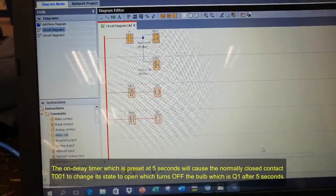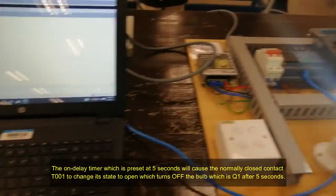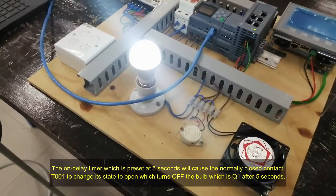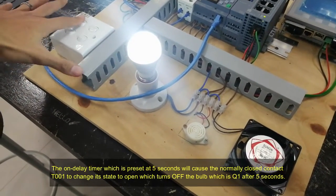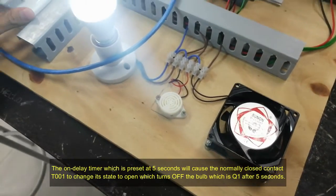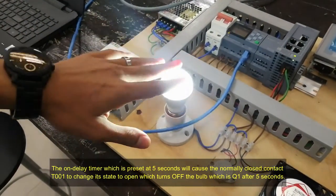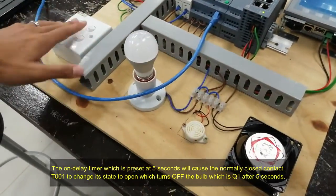The on-delay timer, which is preset at 5 seconds, will cause the contact T001 to change state to open, which turns off the bulb, which is Q1, after 5 seconds.